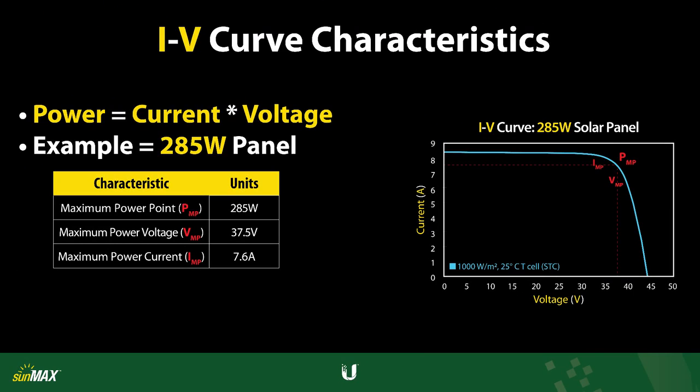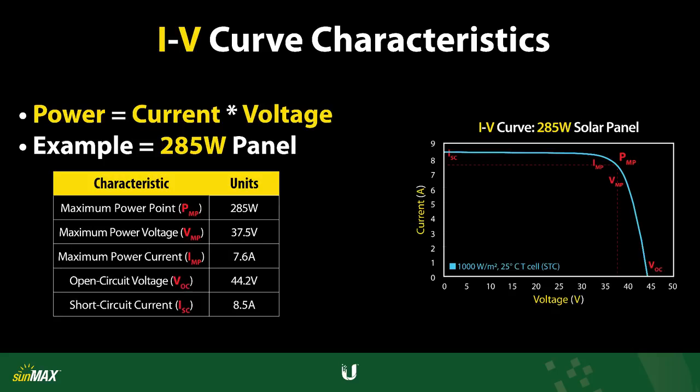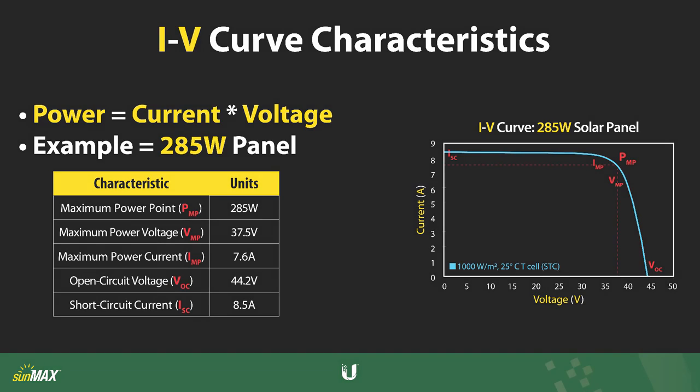IV curves also reference the open circuit voltage and short circuit current, values that are helpful when troubleshooting the equipment, like what voltage to expect of an individual panel when disconnected from the microinverter.